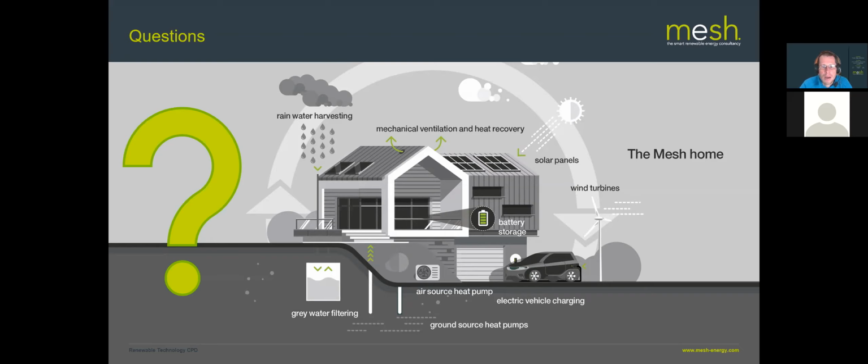But the other way of doing it is a centralized large air source heat pump, and then heat interface units for each flat, and then the question there is about how do you meter it and make sure that the billing's all done correctly and that kind of thing. So yes, they can be very good for flats, and especially if you're looking at trying to reduce carbon emissions and improve SAPs, then a good option.